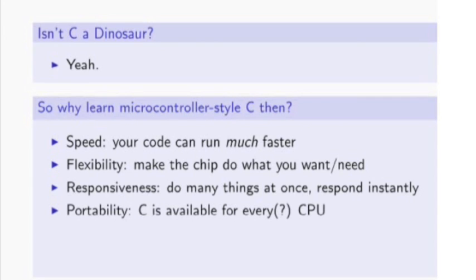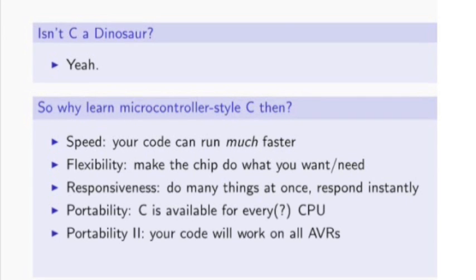More fine-grained, this portability, your code will work on any of the AVR lines. And this is what's more practical for me. I'll often prototype things on the bigger chips, on the mega chips, until I know what's going on, where I have more serial debugging. I have more pinouts if I need them. But then once I find a design is able to switch down to a smaller chip, I'll just copy the code across. And you have to switch some pins around because they're configured differently.